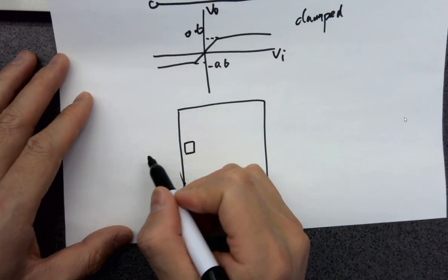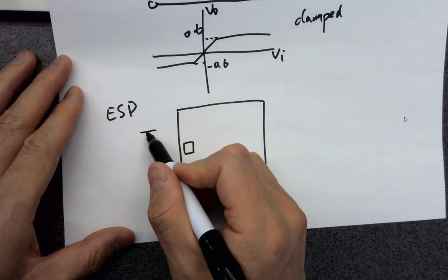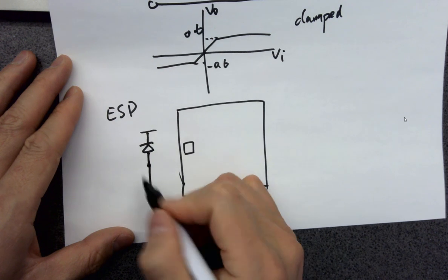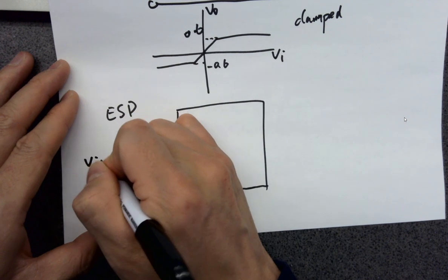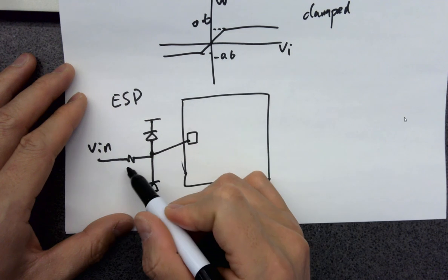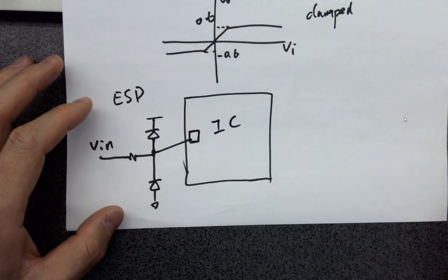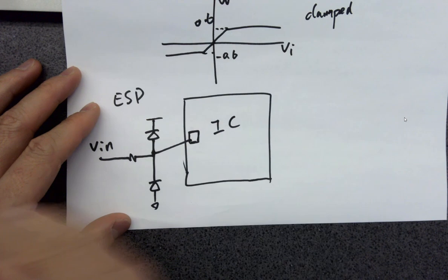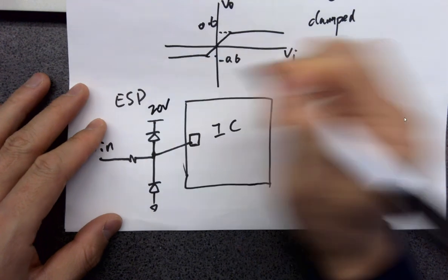and there's an ESD protection circuit. It's formed by these circuits. And here's a resistor at V in to limit the current, before you inject any voltage into the pads of the IC, integrated circuits, and you have these two diodes connected in this way. And for example, it's a 20 volts power supply for the chip.